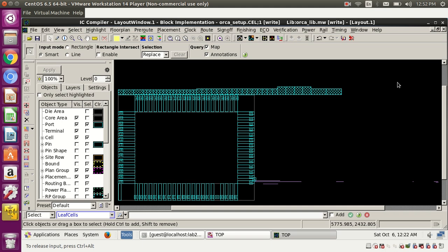Somewhere here it has to be optimistic, it should make it fast. It is not like the standard cell is giving 10 amperes of current, and suddenly M1, because of its width, cannot withstand 10 amperes, so it gives only 1 ampere. That cannot go on, so the current should be equal. That's why as we go above, we make the layers wider.